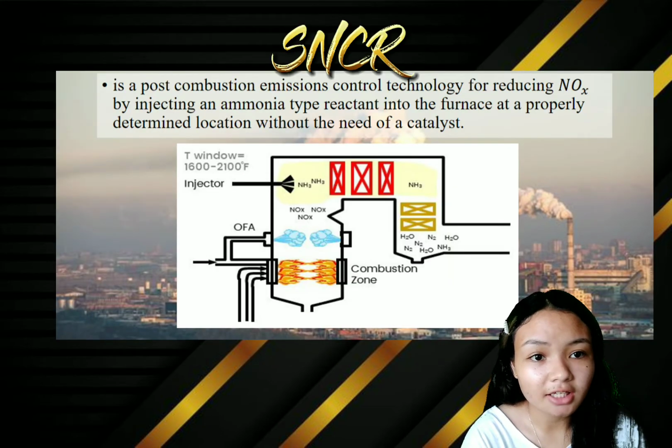Selective non-catalytic reduction or SNCR, on the other hand, is a post-combustion emission control technology for reducing nitrogen oxide by injecting an ammonia-type reactant into a furnace at a properly determined location without the need of a catalyst.